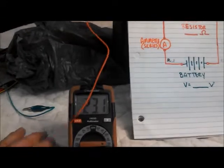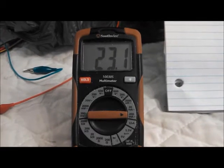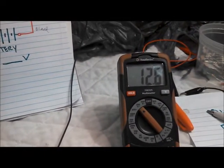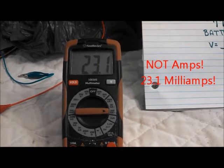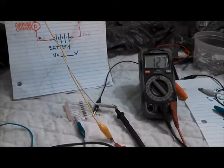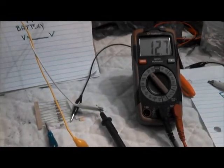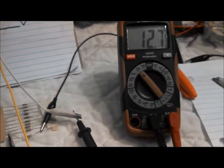and by my calculations I was supposed to get 23.1 milliamps. We'll review the math one more time, but let's remember 12.6 volts, 12.55 volts. That actually gets interesting. And rock solid 23.1 milliamps. Let's see again what happens if I measure the battery by itself though. This is where I wish I had a third meter. All I've done is momentarily hooked up the battery, not across the resistor to check the voltage drop, but I've measured the voltage of the battery.